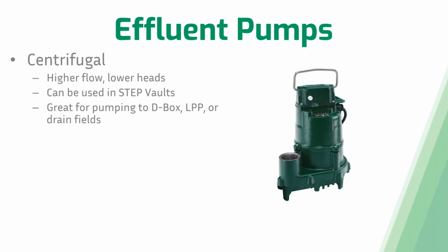A step vault is a sort of housing that's going to be put inside of your septic tank that the pump is going to be inside of. And that step vault is usually going to have some sort of filter to protect that pump from any of the solids that are in that septic tank that may make their way over towards where the pump is located. Now, these pumps are fantastic for pumping to distribution boxes, low pressure pipe, or drain fields, specifically gravity drain fields. They're great for this because of those higher flows, although with the lower head capacities, you're typically not going to use them in systems that require a lot of head pressure.